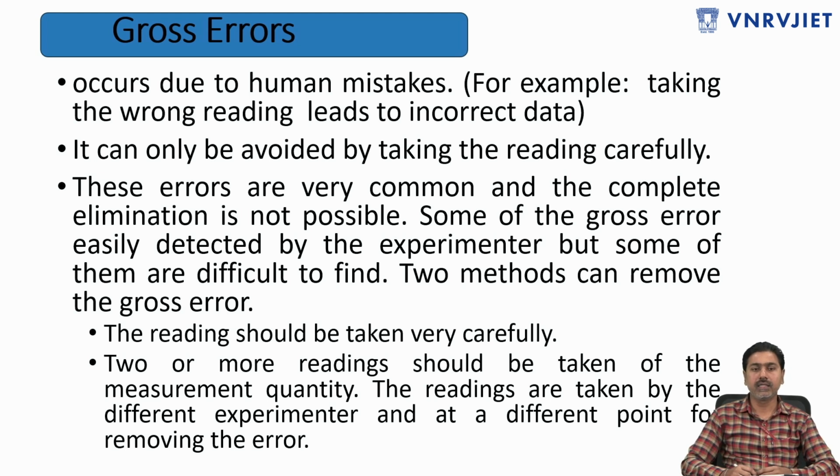So careful recording of the measurement value is required. And also one of the solutions is we can take 2 or more readings to avoid the measurement error. And also we can take the measured values by different people, so we can avoid the gross errors.